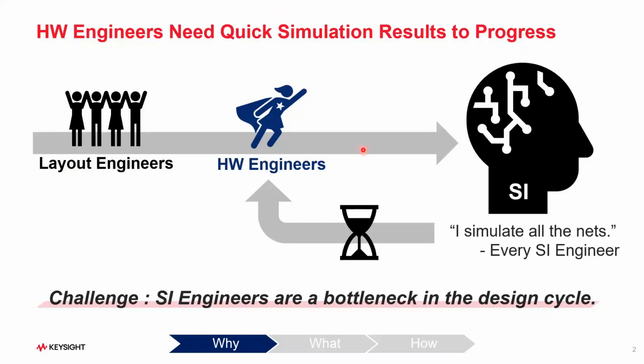Okay, every net on your board file. So you need to wait for his response, then do all the modifications on the board, modifications like track width changes, if there are any issues with the impedance, or any issues with insertion loss data, right? You change the Manhattan length on your layout tab. That's a challenge is what we see. So your dependency on the SI will be more.